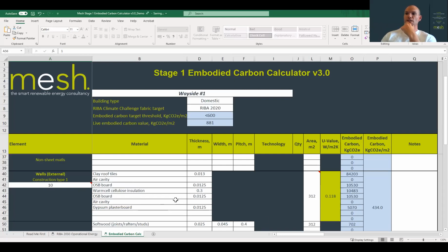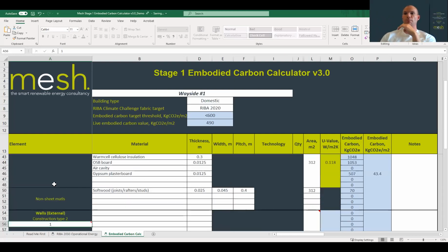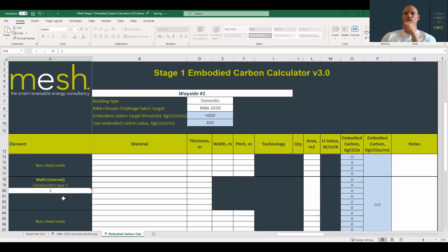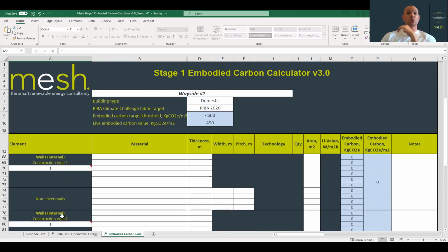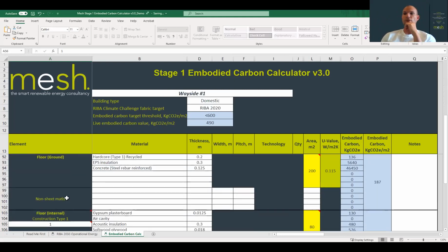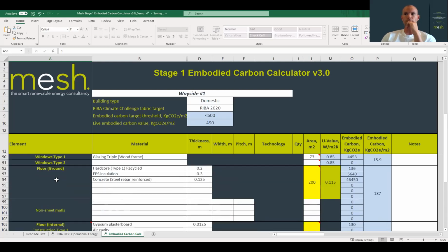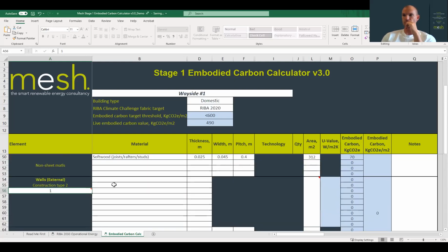Now, this is increasing the walls, but of course, if you increase the walls, you're going to have to go down and do the floors as well. So I'll show you that, but it is pretty obvious. So you've got these multipliers for walls, floors, and you've got internal walls as well. So maybe you have a particular layout of a particular floor, and that's being multiplied. You can multiply that as well. And down here for the floors, the ground floors you wouldn't multiply, there's only one ground floor, but the internal floors you can multiply up also to save you lots and lots of time.